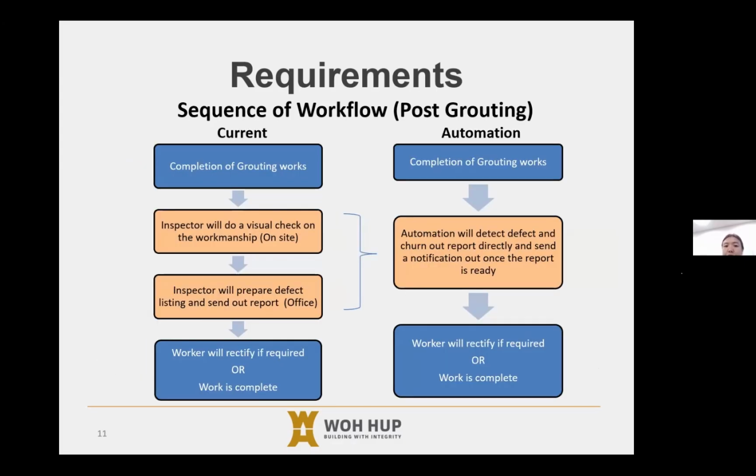Next will be the post-grouting portion, more simplified, because upon completion of grouting works, we will call for inspection. The inspector will come and do a visual check. From there, if our workmanship is okay, they will proceed. That will be the end, the finished product.